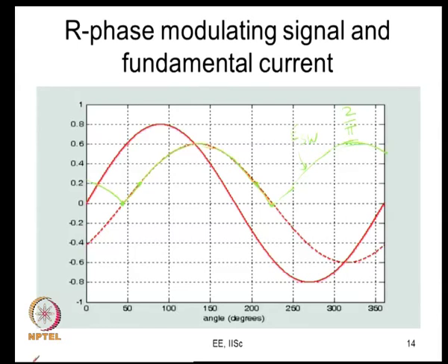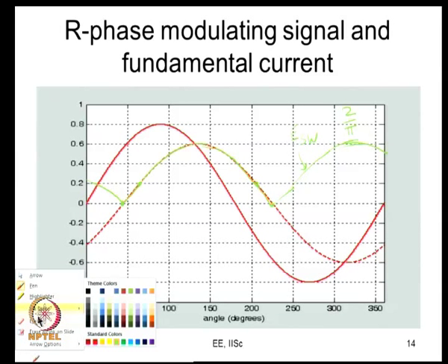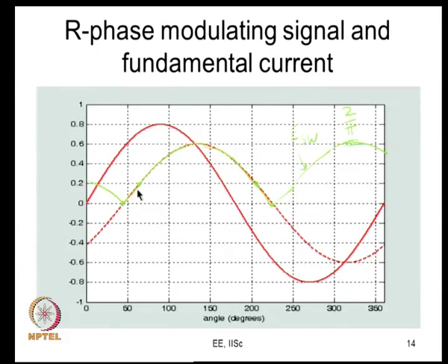And the significant thing that you can note down is, now let us say the current waveform has the same amplitude, but a different power factor. Now, the current waveform may be at a different phase angle. Here it is shown at 45° lag. It may be, let us say, 30° lag or whatever lag. So, what is going to happen is your ESW is going to be similar to that. That is, the wave shape is the same as the rectified fundamental current. It is only going to have a phase shift, but it does not matter, the average value will continue to be the same.